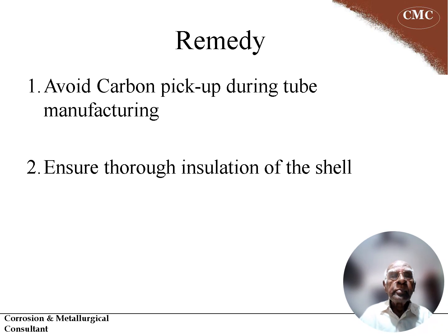Now, the remedy: avoid carbon pickup during manufacturing. This is due to certain operating procedures. When the tubes are made, they are heat treated. During heat treatment, carbon can be picked up. So carbon pickup should be avoided during manufacturing.